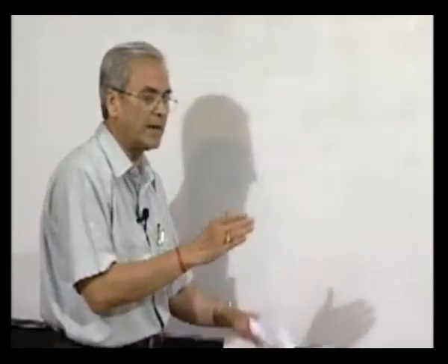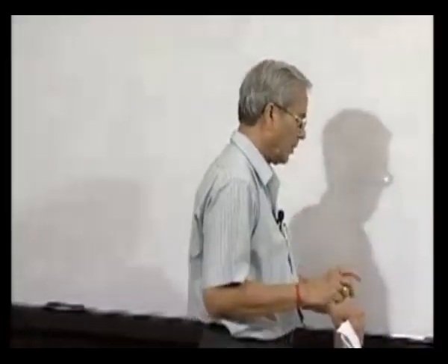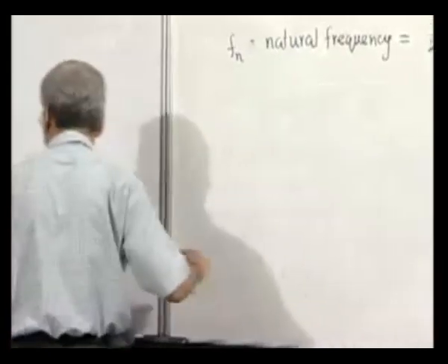So, rather than waiting that velocity will change from one value to the other and basing our system on that change, a better situation we may get if the rate of change of velocity, which you can sense at any instant, is used to operate our governing mechanism. So, I will just give one quick example of an inertia governor.